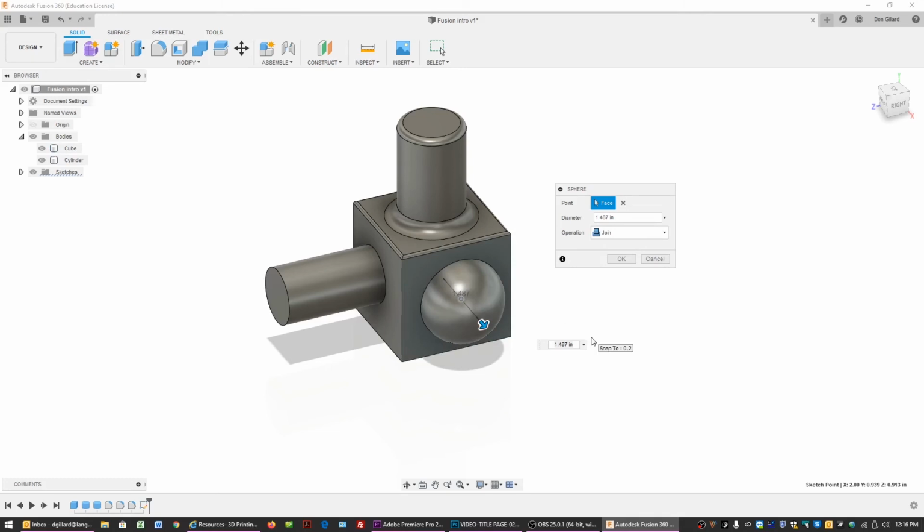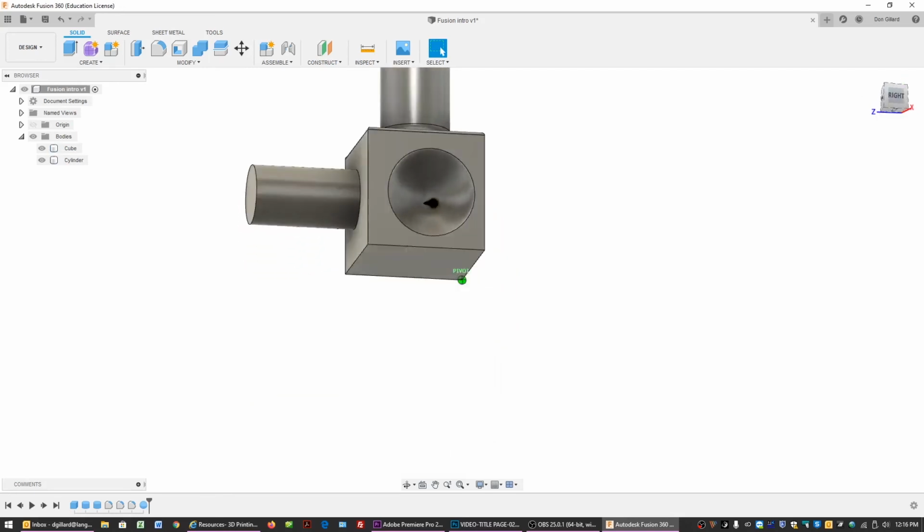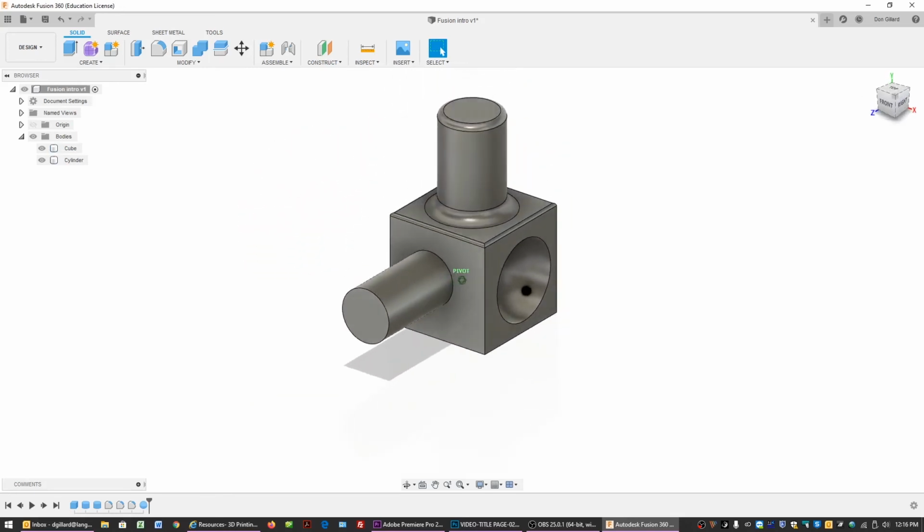By the way, when you go join, there is not an indentation on the inside. If you go join, all you're actually creating is the exterior part of the sphere. Now, if I go cut, it's going to cut that shape out. And I could also do new body, and then it isn't indenting it, but it is creating a sphere. So I'm just going to go cut, say OK, and you can see it's made a cool little dish in the object here.